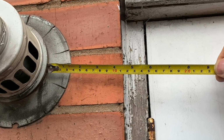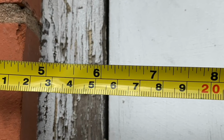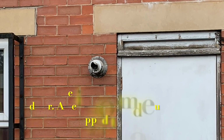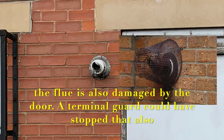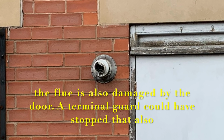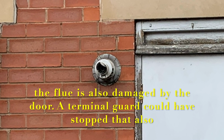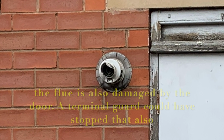Also, it says the flue needs to be 300 millimetres away from an opening to a building, which again is nowhere near. And also, if a flue is less than 2 metres off the ground, it should also have a terminal guard on there. So we've got quite a few problems with this flue system, which is terminating on a public footpath.